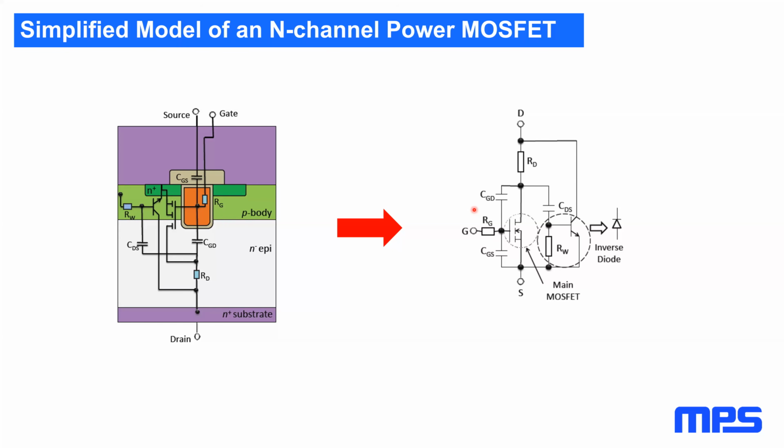Okay, let's see. I have a DC motor and a leg-like mechanism as load, considerable enough, connected to the shaft of the motor. Now when I run the motor by connecting directly to a battery, it attains speed X in 1 rotation. But when the motor is run using a motor driver, it needs 2 to 3 more rotations to attain speed X. I guess this is due to ramp current. Is there any solution to get the desired speed in one go?